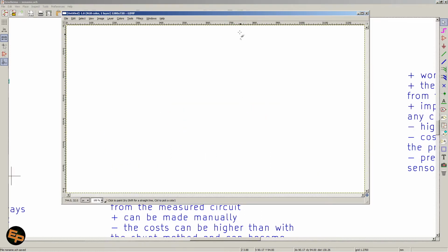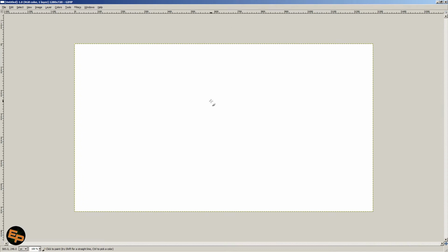So I'm gonna make a drawing for you to understand what needs to be done. Let's say that you have a circuit like this, right? And there's a current passing through here, and you want to measure this current. And of course it needs to be an alternating current. Like I've said, it cannot be a direct current because induction doesn't work in direct currents.